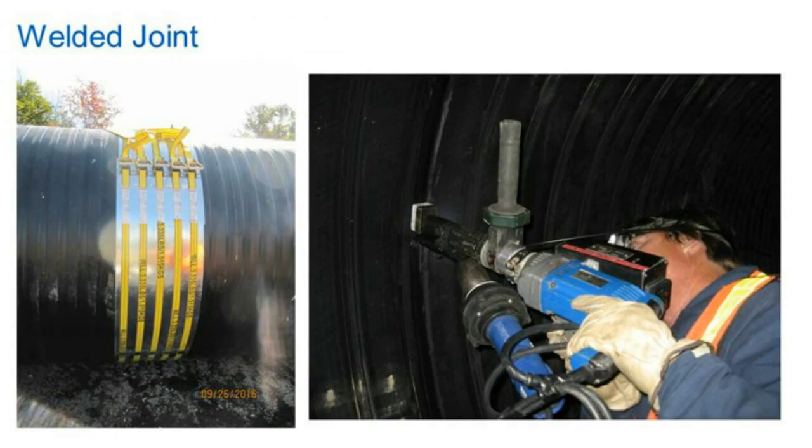So on a welded joint, you'll see that there's a band here. We want to talk about that. When the welded joint is selected or necessary, the pipe will come with a 90-degree notch on the ends for lining the pipes up. And then the first step is, as they line that pipe up, now we're going to have to use an alignment band to hold that pipe in place. So as you see on the left there, that band is put into place, and that's going to help hold that pipe during the time that the technician is there. Now, this is also going to help keep from dust and dirt and actually even wind getting into that joint